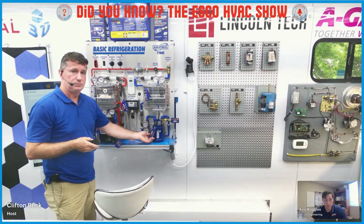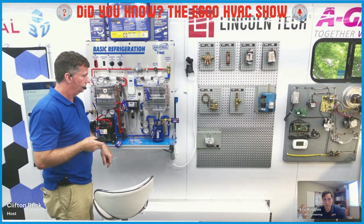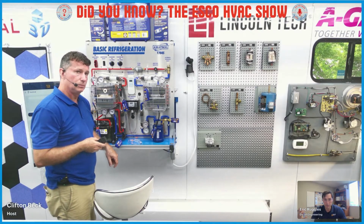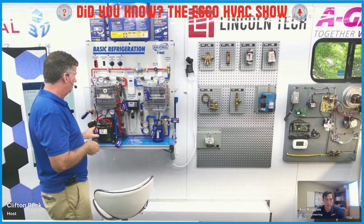So that's your psychrometer. That's going to the air side. It's got a long probe on it, and you're going to want to put that in your supply and return air streams so you can get your dry bulb, wet bulb, relative humidity, and dew point of your airs. So we can compare those, get the enthalpies, and actually determine what the capacity is of the system and what efficiency it's running at.